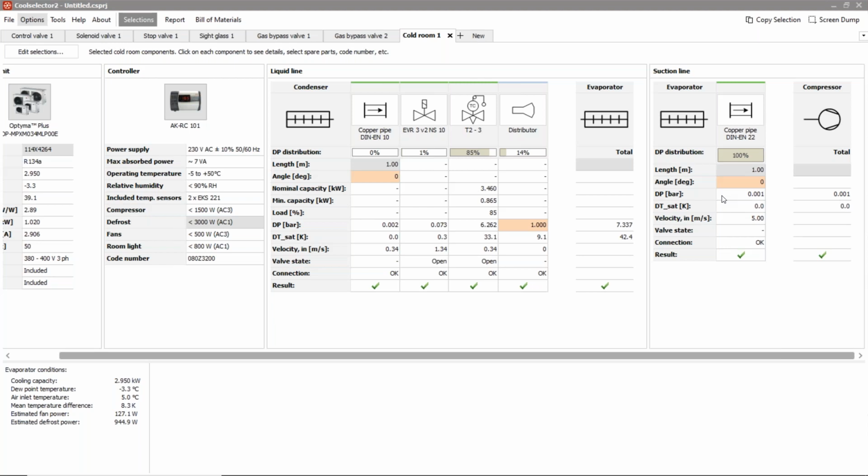This information should be given by the panel manufacturer, but you also have to check the thermal conductivity, because it's a matter of heat transfer, and that heat is added to the heat load of your cold room. You have to be careful when you design a system, making sure this factor is also considered in your heat load calculation. Based on the heat load output, you then select the condensing unit.